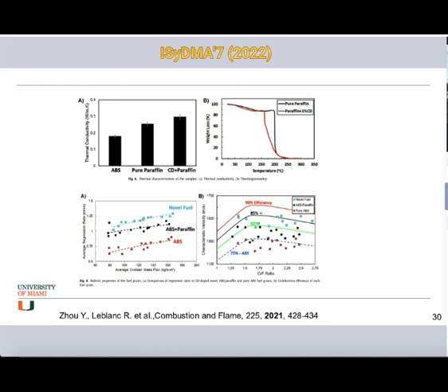And finally, for A and B, this is mainly related to the novel fuel compared to the same, I would say, polymer, paraffin, ABS plus paraffin, and you can see the novel fuel gives us an average, most important regression rate. And on figure B, in terms of efficiency, all the points on the curve are the experimental ones, and the calculated one is the traced one. And we can see that using the carbon dust in our system, we have 90% efficiency. So this is quite important to increase the combustion rate in the system.